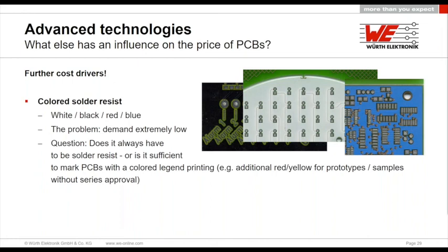And if we want to do green again, this means taking the other solder mask from the machine, cleaning it thoroughly, setting up the new solder mask, for example, green again, and doing the testing to see if everything in the process works correctly. So this creates quite an effort in manufacturing, and therefore this is being placed onto the cost of your panel if we change the solder resist from green to any other color.